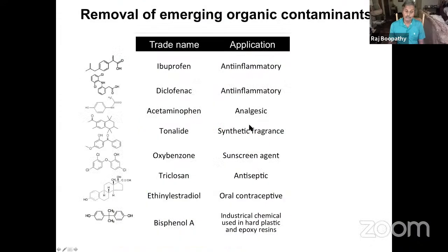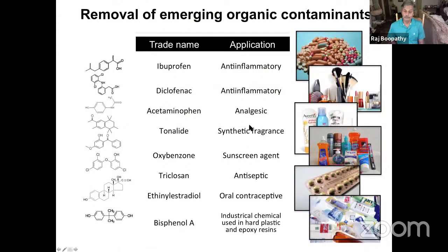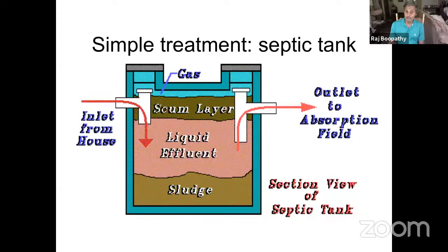And there is a list of chemicals that this constructed wetland can remove. A lot of antibiotics included, the antimicrobial compound triclosan, then common over-the-counter pharmaceutical compounds, those can be removed, but in the conventional plant, it's not. So this is where the Western countries are geared towards now. Sewage plants now, they're combining with wetlands treatment to take care of the domestic wastewater.